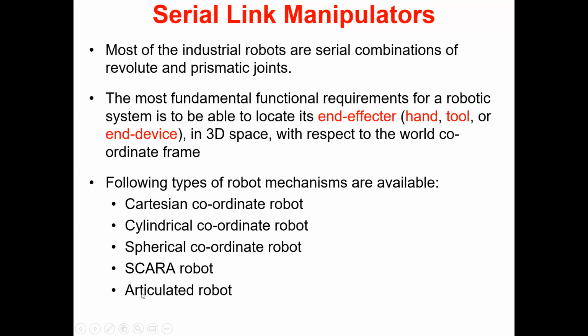SCARA is again kind of articulated, but not exactly articulated. It is the second most widely used one, or Cartesian robot. Cartesian ones are also used very much, but Cartesian robots are not very generic. You can use them for very specific purposes only, whereas SCARA and articulated you can use for applications in general, particularly the articulated one.